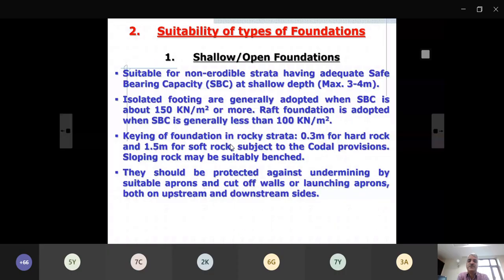I know of one section which was with me, Karur Dindigul in Southern Railway, where a new line was built and we took over. Otherwise it was a dry area, but there were very heavy rains during that year and there was erosion. So if you see along the track, this was rail, then sleeper, below that some ballast, and this box was hanging from the track, with nothing below. Around 8-10 such boxes were hanging. Some had fallen, some were hanging with some support here and there.